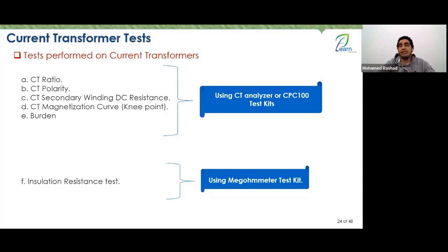The second thing is if it was connected to protection, we also agreed that you have something called zones. And when I said zones, I didn't mean the word distance, but I meant zones as in you have something called forward zones and reverse zones, meaning there are protections that protect my line in the forward direction, which looks towards my line or my feeder that it protects. And there are some that look in the reverse direction towards the bus and towards what is connected with the same feeder of mine on the bus.